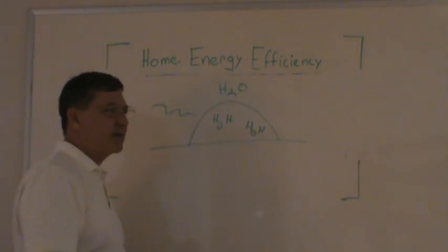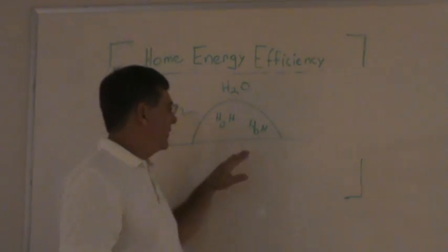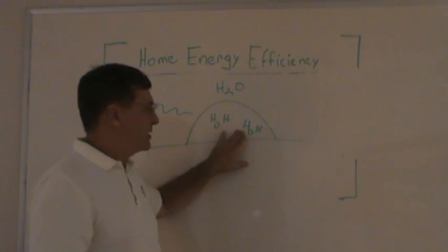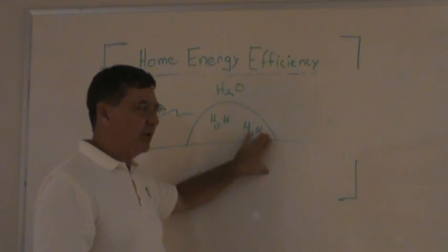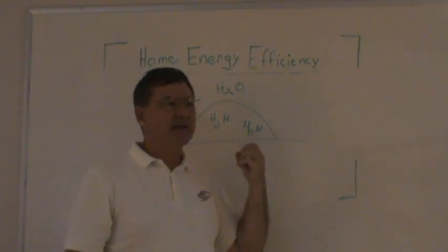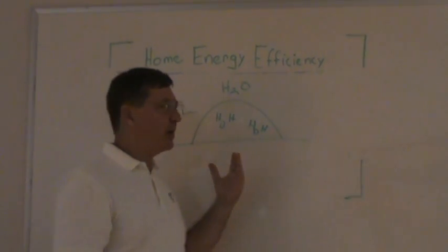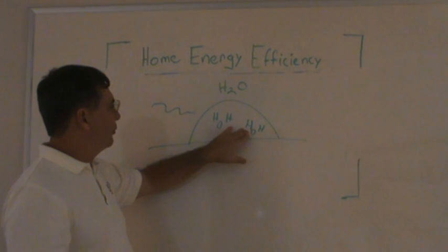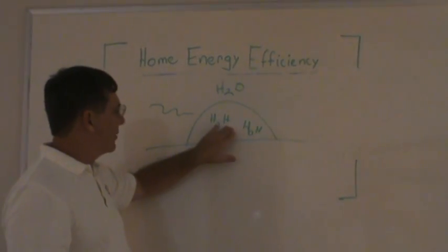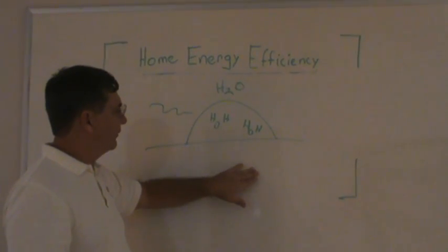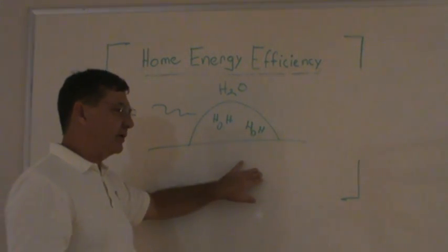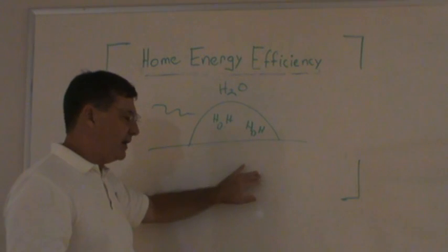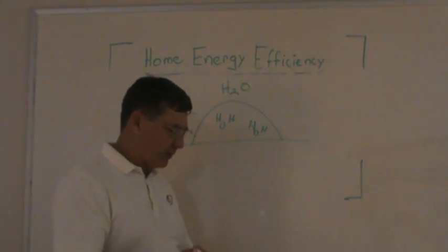And when that happens, there's a change of state that takes place. In order for a water molecule to go to a gas, it needs heat, and it picks up heat wherever it can. It will pick up the heat from other water molecules and also from my skin. And so that's an example of talking about change of state and a refrigerant cycle.